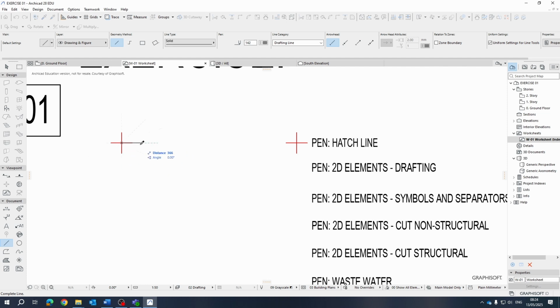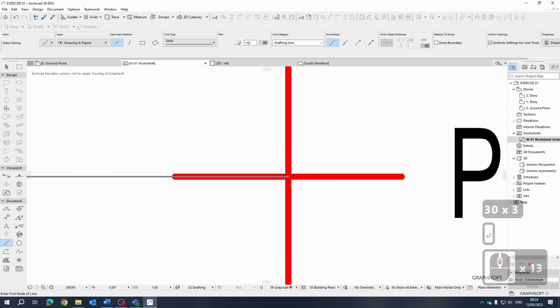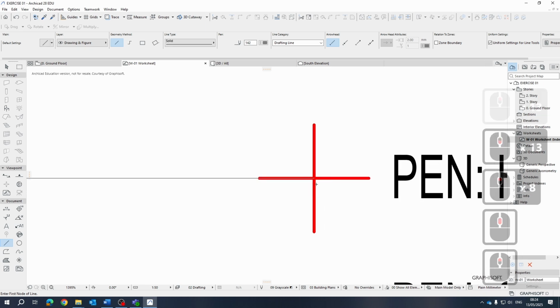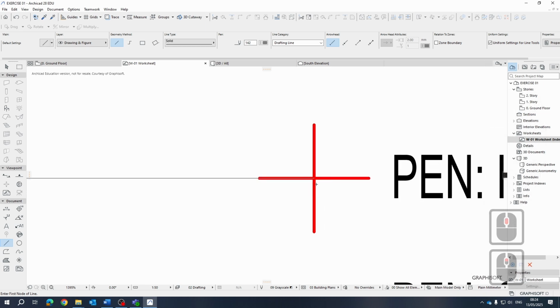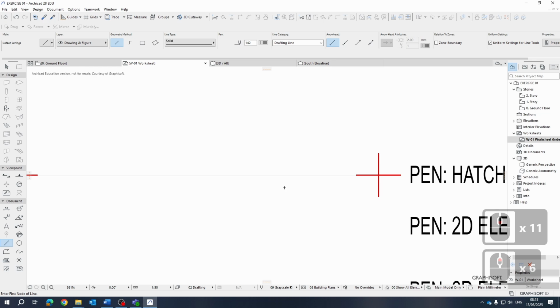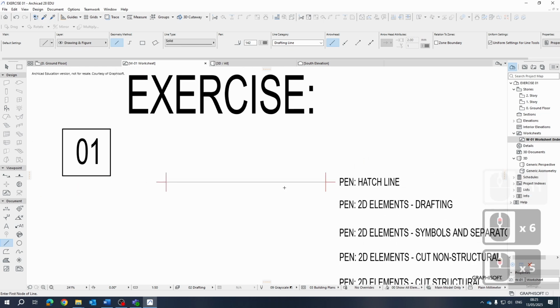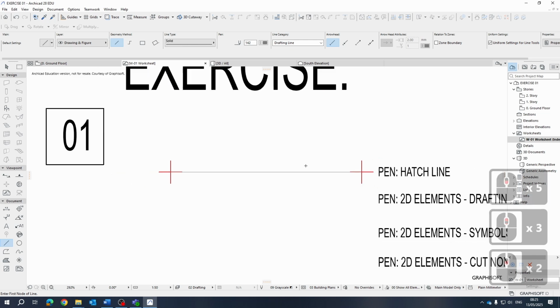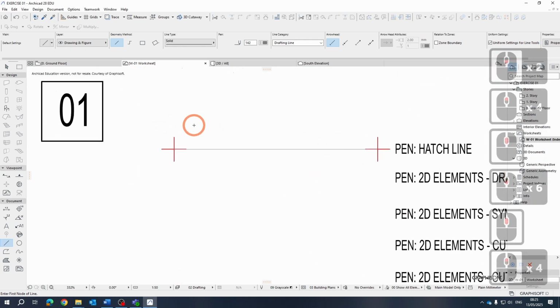Okay, so once you've activated the drawing command, if you draw in this direction, you can type in a dimension and you'll notice it'll create a bit of line work to the correct length. Please note that lines work very similar to working with Inkscape and GIMP. You have an order of where they sit. So when you keep drawing, the latest object will always sit above the other object, and you'll have to use draw orders to send things to the front or back. But we'll get to that later on when we start tackling more of the nuanced types of workflows.